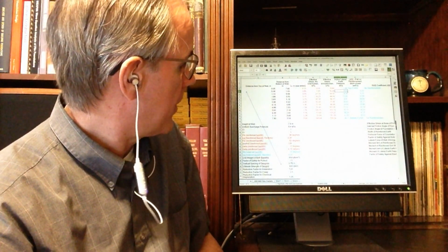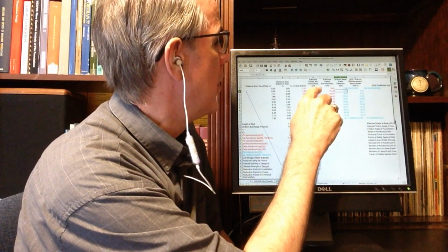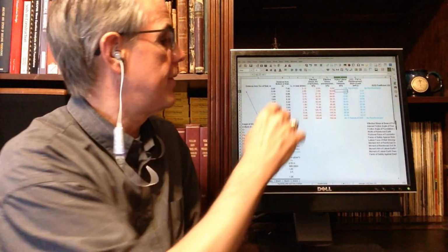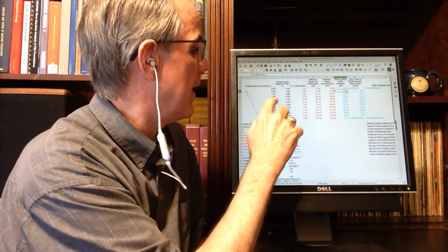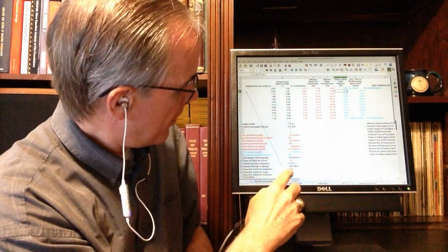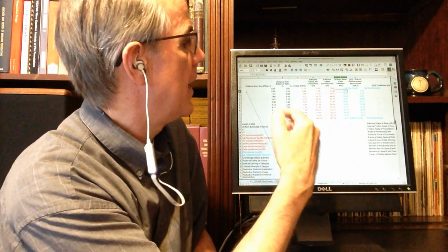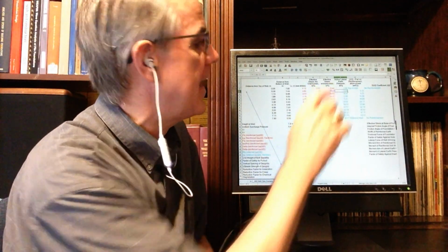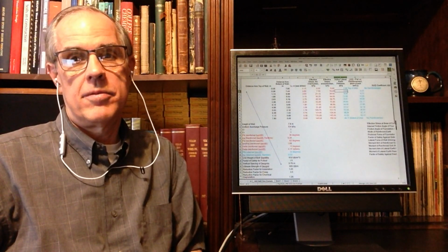Then from there, the effective stress, no overburden, is simply gamma times the distance from the top down, and gamma times that, and gamma times that, all the way down. That's all that expresses the overburden. By the way, I put all of my variables for the soils down here. The effective stress with overburden is simply taking this and adding the overburden, or the uniform surcharge, with it.